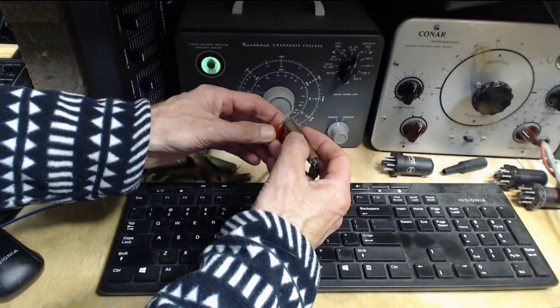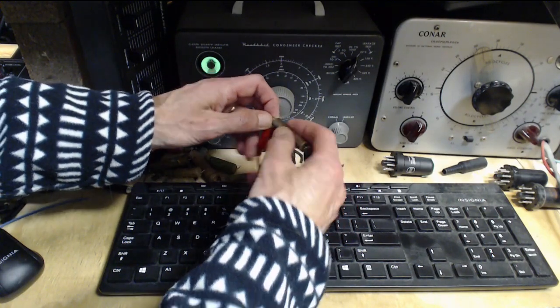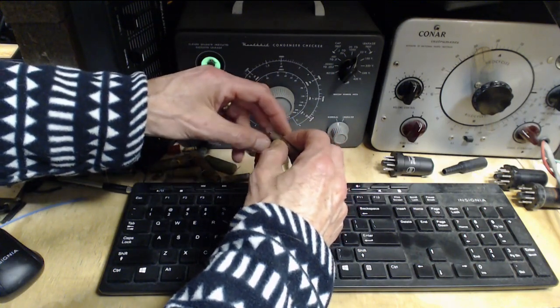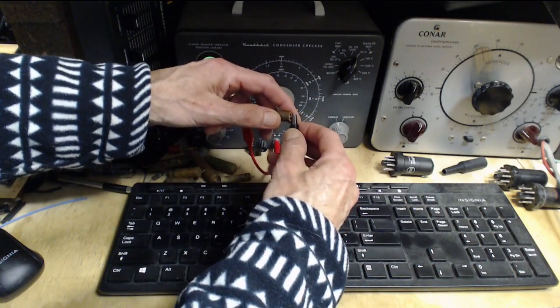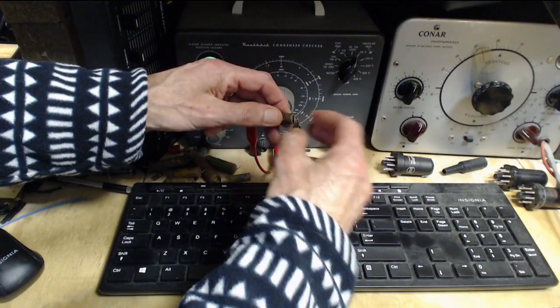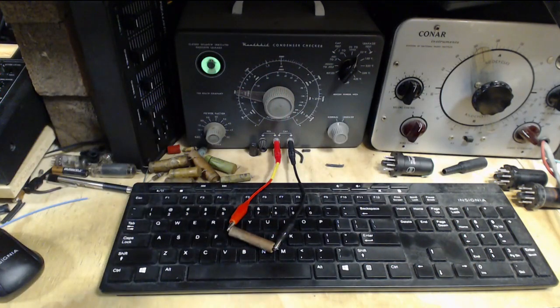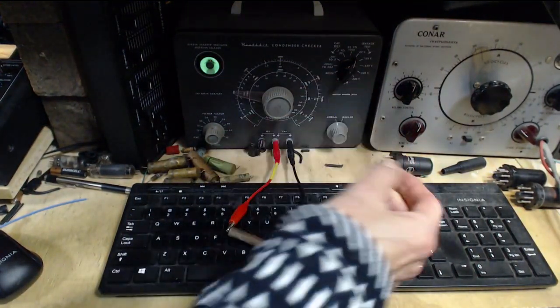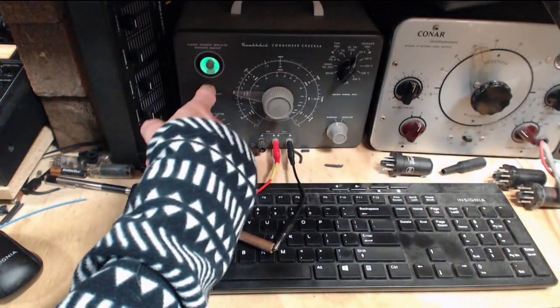Newer equipment, especially computerized equipment, chips, all that kind of stuff, has no high voltages in there. And the idea of testing a capacitor from one of those things with high voltage is a little bit odd. Today they use other tests. ESR is more important for the tiny components, I believe. That's the deal. Okay, here we go.